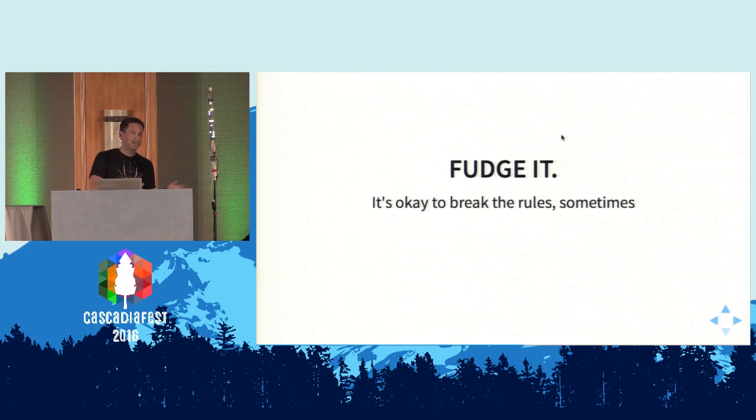But there's rules. You can break them. I'm breaking them here. Kind of a rule of thumb for me is 16 LEDs or less, and you can actually forget everything I just said. You can power them directly. At 16, you can actually use the onboard 5-volt regulator on the Arduino without much of a problem, as long as you don't turn them all on bright white, which most people don't anyway.